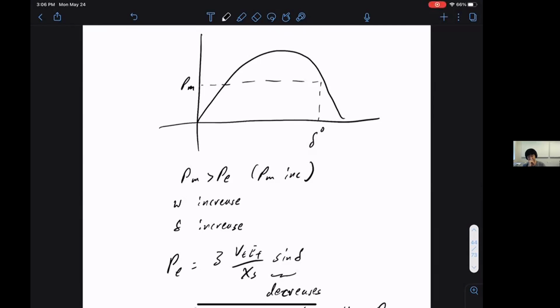So between these two angles, we're mostly going to use the left one instead of the right, right? Yeah, we'll never use the right angle. In a power system, you'll never see two buses with an angle larger than 90 degrees. That just does not happen.